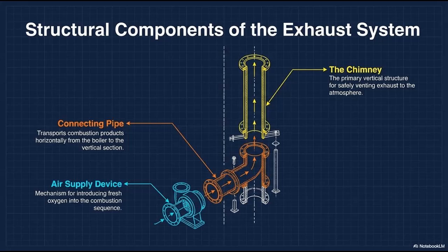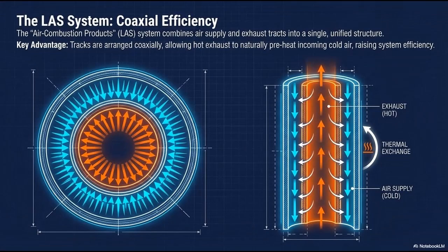It's wild. So if you have a standard 24 kilowatt boiler heating your home, that machine needs to inhale almost 100 cubic meters of fresh air every single hour just to run safely. That is the entire volume of a large living room. Sucked through the boiler and pushed out the roof every single hour. And historically, this just wasn't an issue. Older homes accommodated this massive air exchange because they were essentially giant architectural sieves. The house provided a constant, if inefficient, stream of fresh air for the boiler to consume.